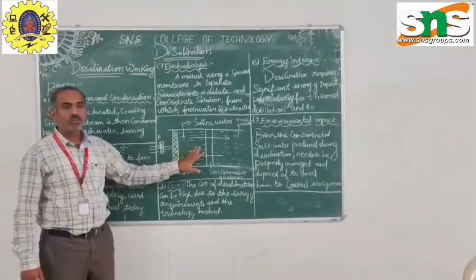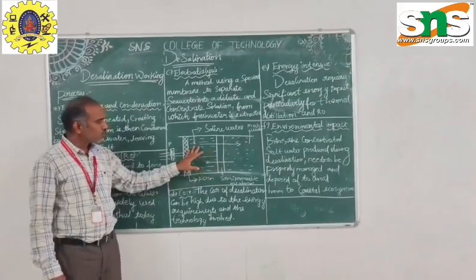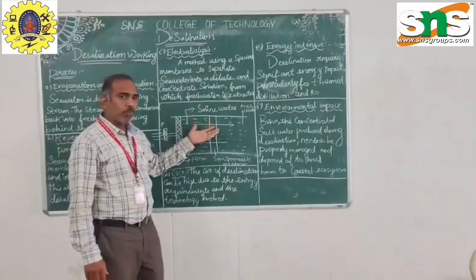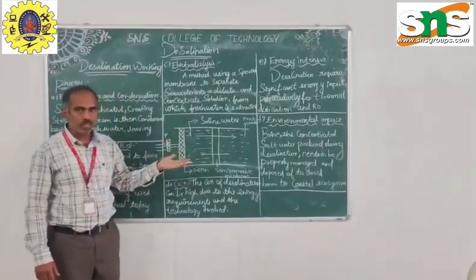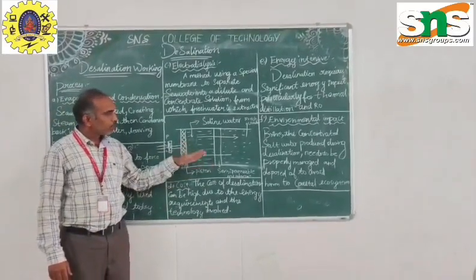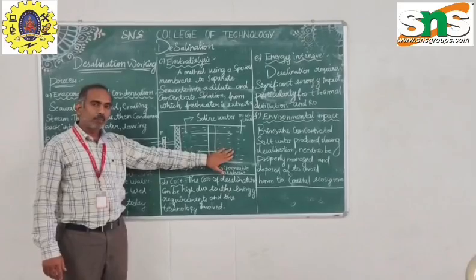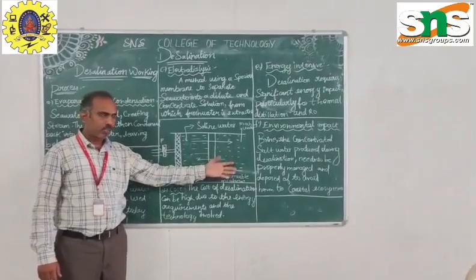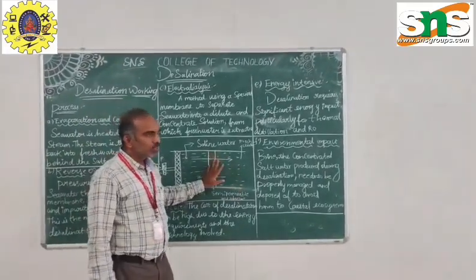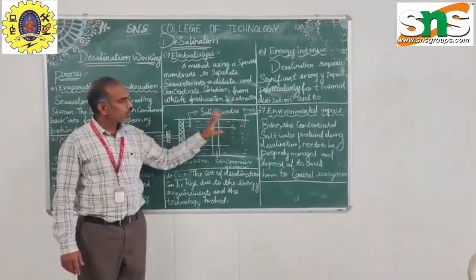Nowadays we are using it for domestic water treatment systems, and the better one is reverse osmosis. For the industrial problem, hard water is converted to soft water, and we can use the ion exchange process and sodium exchange process. Compared with those processes, we can get a purified form of water with less than 10 ppm of salts in the outcome water. So this is one of the best ways, and it is economically and environmentally very suitable.